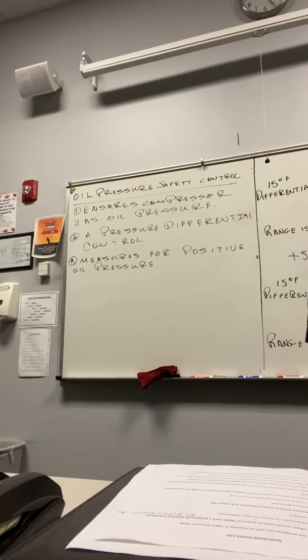The oil pump suction pressure is actually the suction pressure of the compressor. This means the true oil pump pressure is the oil discharge pressure minus the suction pressure. For example, if the oil discharge is 130, and the compressor is at 70 psig suction pressure, the net oil pressure is 60. This is a usable oil pressure and it's positive. It means the oil's moving through.